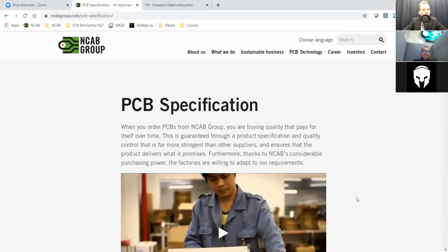So what are the design decisions that people make that result in costs that rise without being aware of it? Let's say they design a PCB and maybe they place holes in the pads, which do cost more to do properly. What are some of the other things that you have seen that were mistakes on the part of the designer? Well, mistakes, as you say, a hole in the pad could be done, but it's probably driving cost, and it's also not creating the effect you want on it.